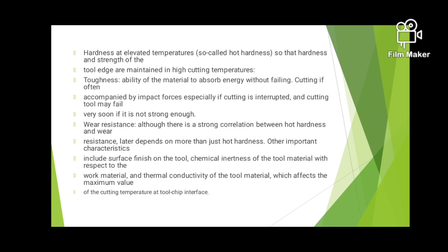Hardness at elevated temperature, so that hardness and strength of the tool edge are maintained at high cutting temperature. Toughness, the ability of the material to absorb energy without fracturing, accomplished by impact forces, especially if cutting is interrupted, and the cutting tool may fail very soon if it is not strong enough.